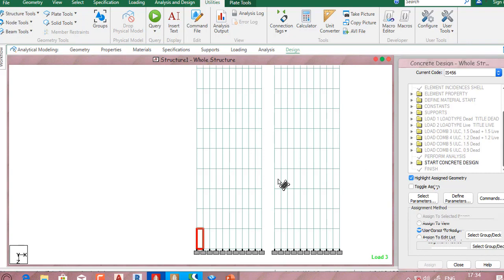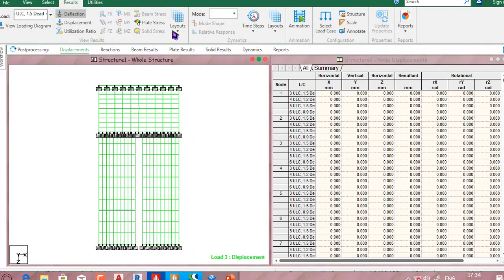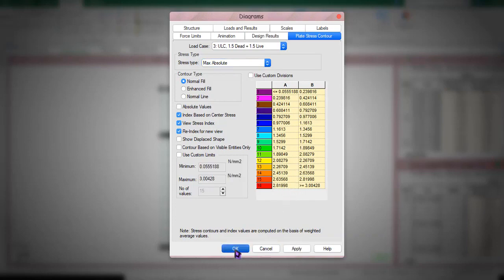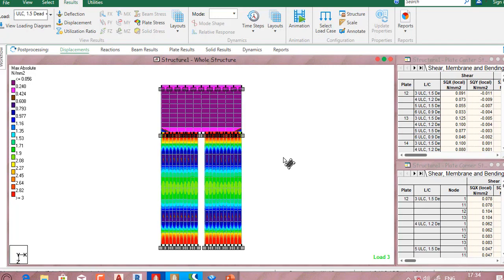As you can see, the basic concept of FEM is meshing. If I didn't mesh the slab, I'm not getting accurate results for the design of the slab. If I mesh it, I'm getting errors or some crazy design in the area of steel of the slab. So what we usually do is we don't design slabs using STAAD Pro. All we do is go into post-processing and find out whether the stress in the plate is adequate to provide the thickness for the slab. That's what we do in STAAD Pro, not design of plate. The design of slab is a total maniac and no one's going to follow that. So that's a sad story in design of staircase in STAAD Pro.